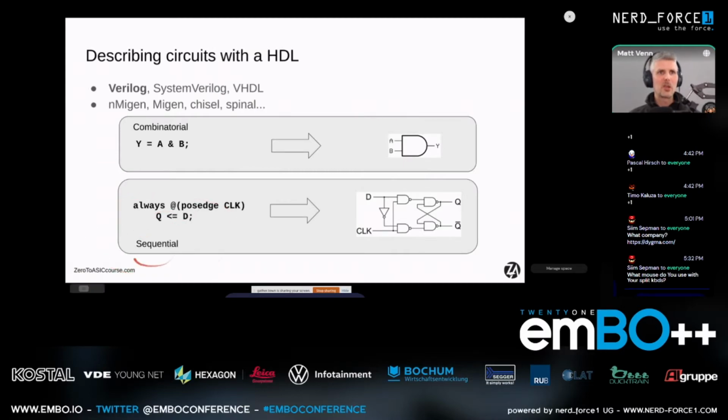And we also have sequential logic, which is usually clocked, so things only change on the clock. And we often have combinations of this: some combinatorial logic that does some calculation, and then we clock it all into a register and use it sometime later. So in a CPU that you're probably all used to using as embedded engineers, we've got our registers, which are all made of flip-flops. We've got our ALU, and that's all mostly combinatorial logic. And then we've got a load of sequential logic for dealing with hashes and FIFOs and clocking instructions through the CPU.